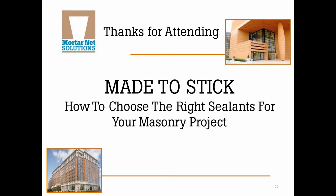Okay, great. We have another question. What is the best sealant for anchored natural limestone wall panels? Assuming you're talking about the joints between the panels, MPE-1, a modified polyether, would be great for that.